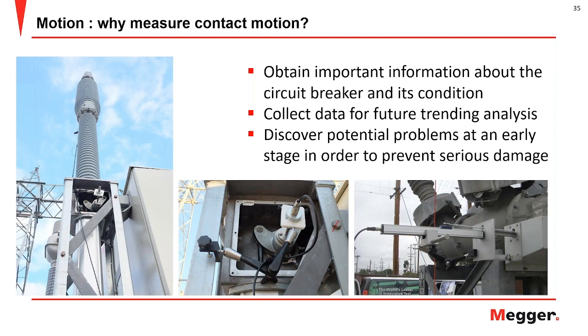And that is dependent on the type of the breaker that is used to extinguish the arc that is generated after the contact separation until the next zero crossing. So it is important to interrupt the current to prevent a restrike. This is accomplished by making sure that the contact moves apart far enough and with enough speed.